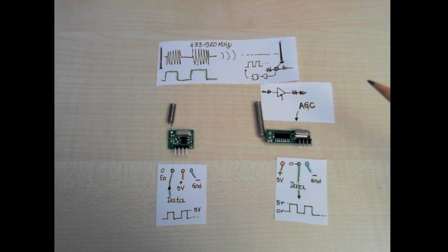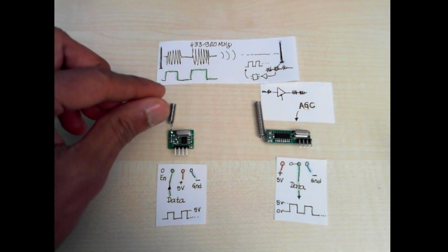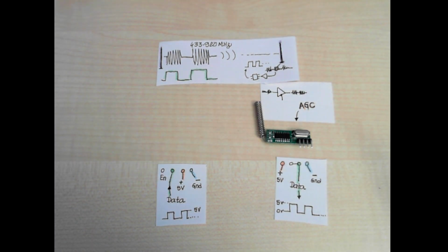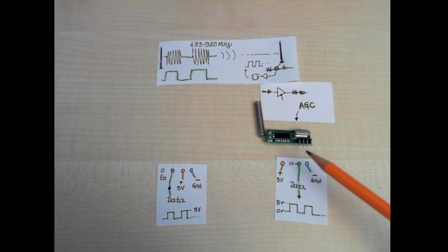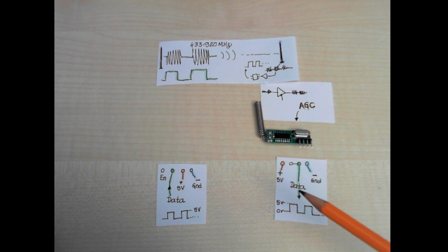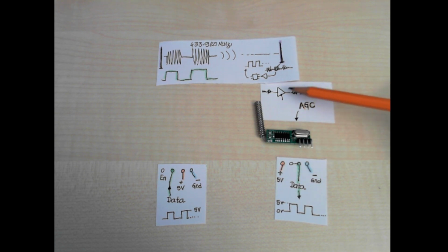And this is relevant for our experiments because you will realize that if there is no transmitter in the picture, your receive pin would still be pulsing out some signals, and this is because you do have several modules in the environment and some weak signals may reach this module, which the automatic gain control now amplifies and uses.